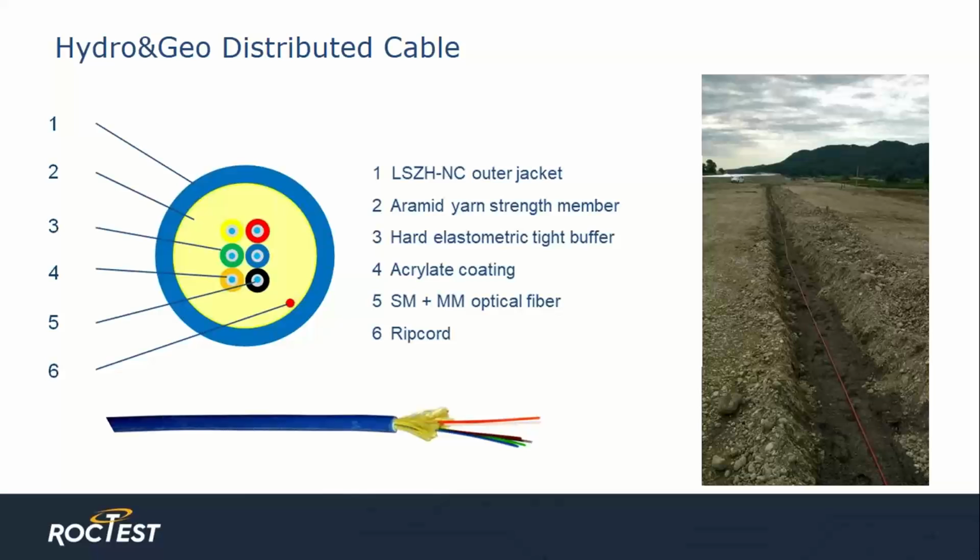The sensor is particularly suitable for geotechnical applications with different methodologies of installation. For example, direct burial in the underground, integration into geotextile, or surface installation in grooves. Thanks to the robust package design, the Hydro&Geo cable offers high tensile strength, crush resistance, water tightness, chemical and abrasion resistance.